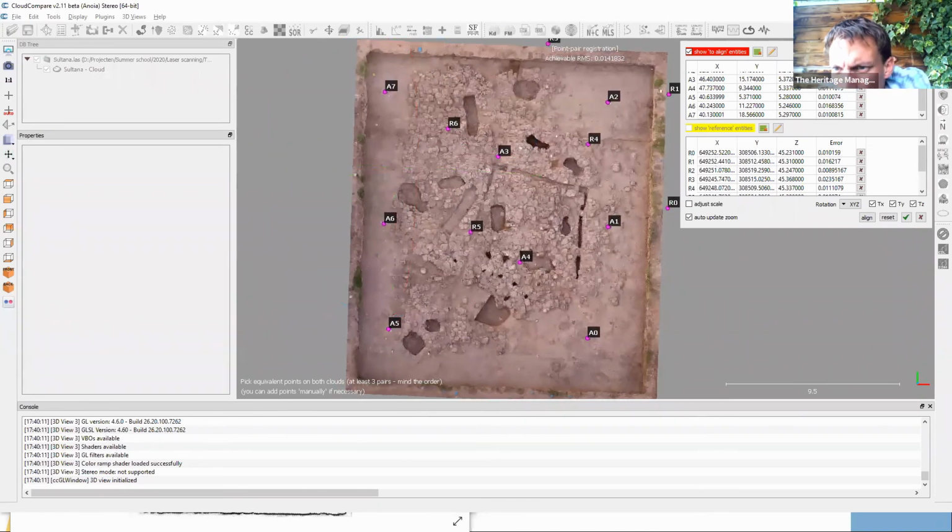So what we should do now is we should make sure that we have our rotation set correctly. So assume that we are working here with laser scan data. You should say, okay, we will only rotate around the z-axis. So we will rotate in our horizontal plane. If I say, okay, I do it in all directions, I can just rotate my point cloud in all directions. And that's definitely something we don't want to do here. So I set our rotation to only in the z direction.